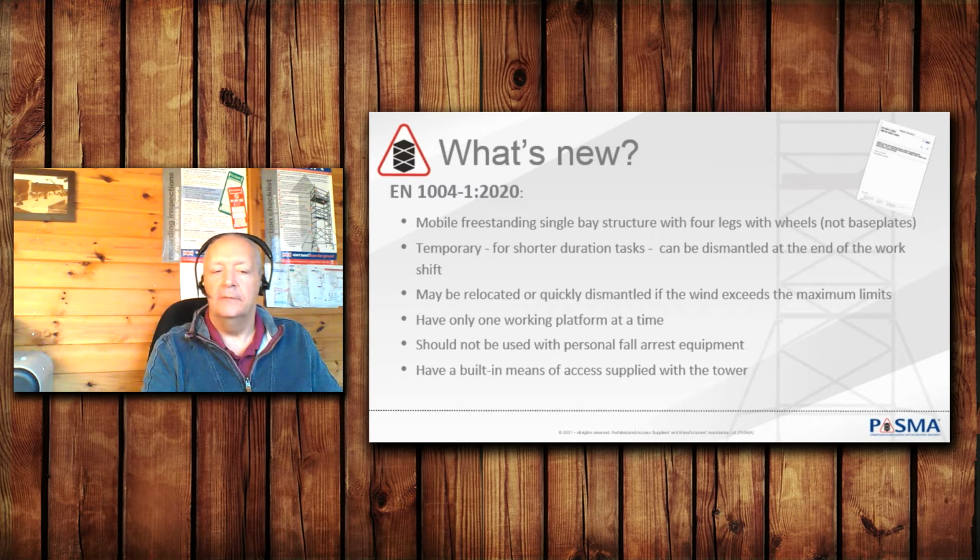They're intended for temporary works of short duration where they can be taken down at the end of the work shift. If the wind conditions exceed the maximum permitted, then they can be moved indoors out of the wind or quickly dismantled. They must only have one working platform at a time. They're not designed to be used with personal fall arrest, as they have built-in collective protection. And they must be supplied with a built-in means of access to the platform.